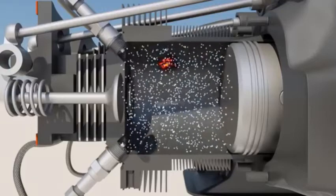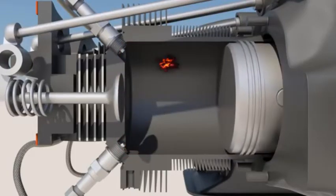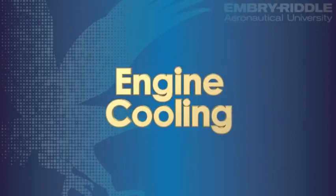Just as you'd expect, pre-ignition is simply when the fuel-air mixture is ignited prior to its normal time. This phenomenon usually occurs because of a lingering hot spot on the cylinder wall, usually caused by a carbon deposit that is hot enough to ignite the fuel-air mixture. Even when the engine isn't detonating or experiencing pre-ignition, the temperature of an engine can get quite hot.